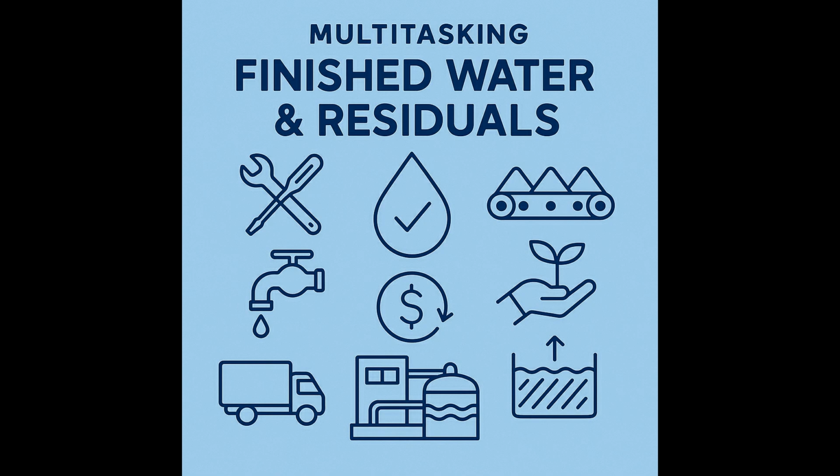Not ideally. That's where bench testing comes in. It's often called jar testing when applied to sludge. It's a small-scale laboratory test where operators take sludge samples and mix them with small, measured amounts of different polymer types and doses. What are they looking for?